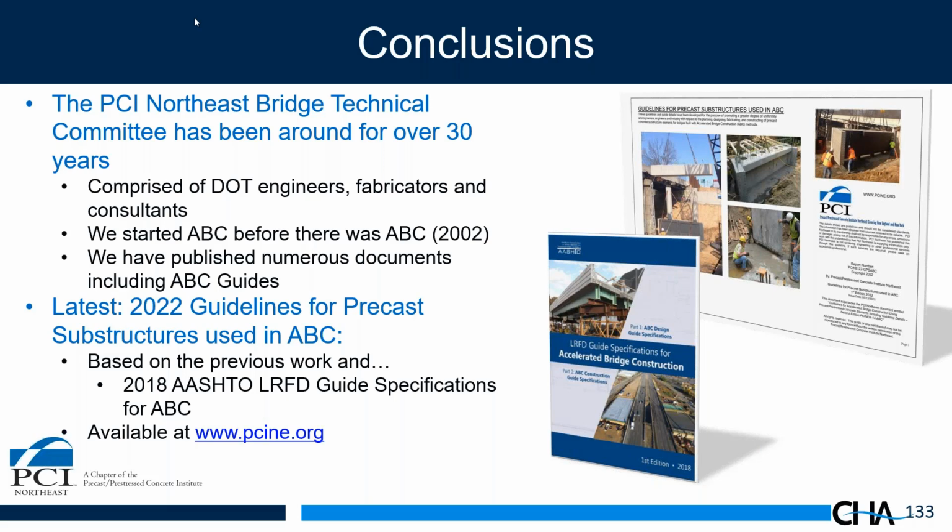The question came in beforehand about what are the difficulties in subgrade requirement preparation for precast concrete spread footings? Yeah, the key thing is we've seen people try to prepare the subgrade perfectly level and set the footing down on top of the subgrade. It can be done, but it requires a high level of accuracy of getting that subgrade leveled off, and there's no adjustability. So we recommend setting the footing 3 to 4 inches above the subgrade. So normal preparation of subgrade can be done with the normal tolerances you have for preparation of subgrade. Set the footing 3 or 4 inches high on shims or leveling devices, and then fill that void with flowable fill to complete the connection.